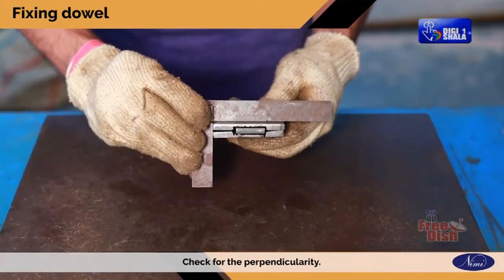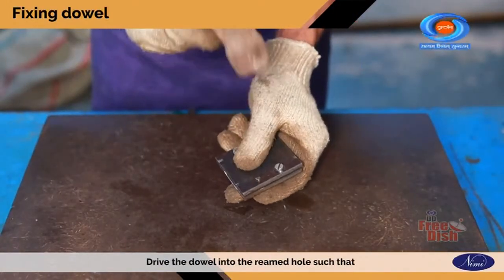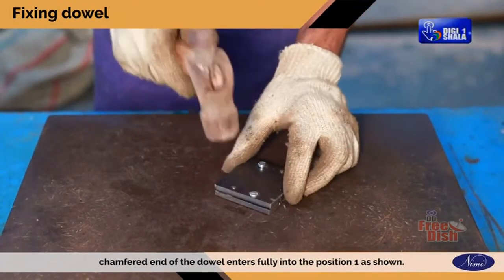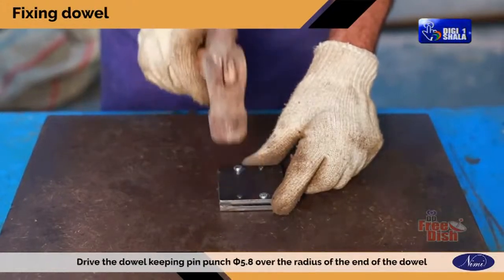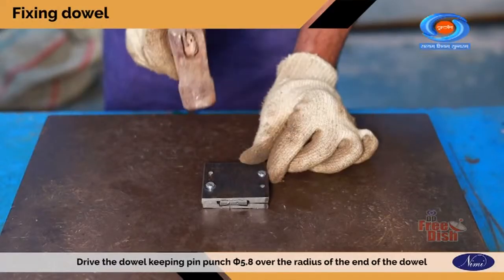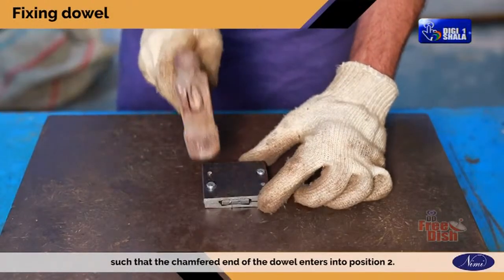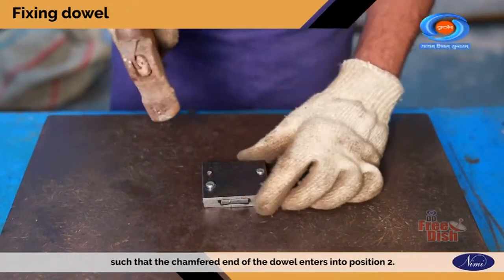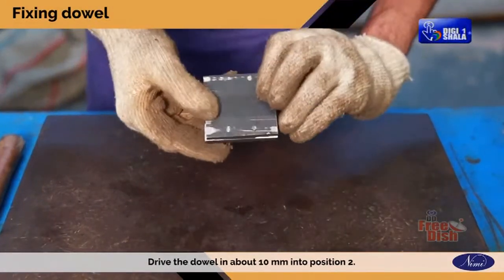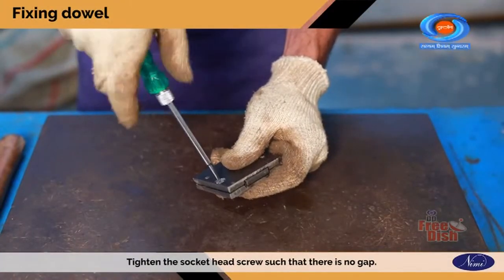Check for the perpendicularity. Drive the dowel into the reamed hole such that chamfered end of the dowel enters fully into the position 1 as shown. Drive the dowel keeping pin punch diameter 5.8 over the radius of the end of the dowel such that the chamfered end of the dowel enters into position 2. Drive the dowel in about 10 mm into position 2. Tighten the socket head screw such that there is no gap.